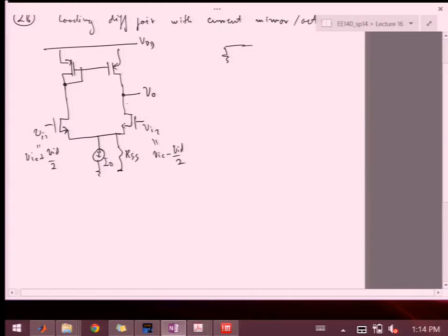But then this guy goes here where the load gain is pretty low. It's this gm into this 1 over gm. So it really maps this voltage right into this gate over here. And then I'm driving this voltage, and again I have gm times whatever the output impedance is on this node. So intuitively, the two signals are adding up through two different paths. But we'll see that as we work out the small signal model, you're actually going to get something like that.